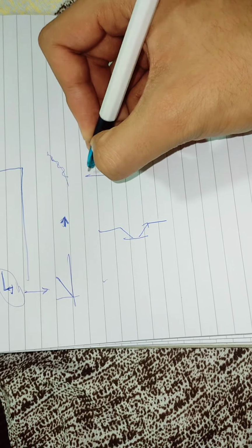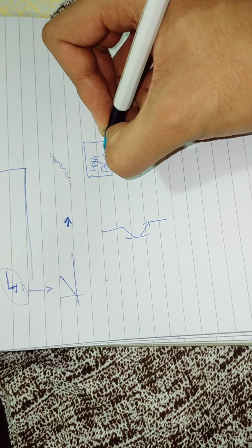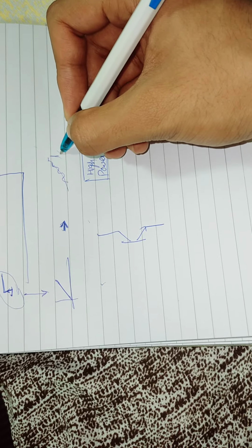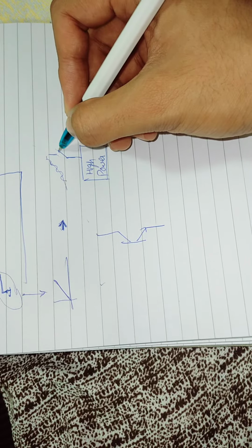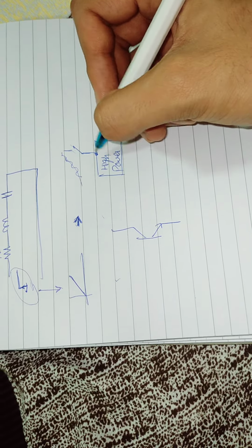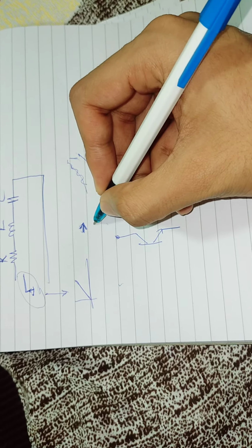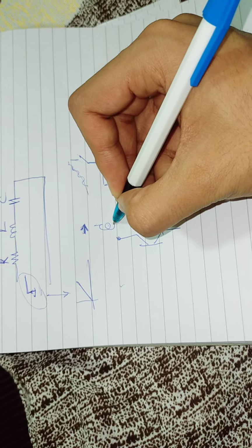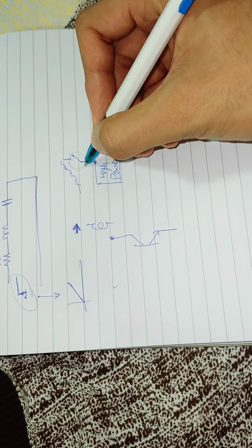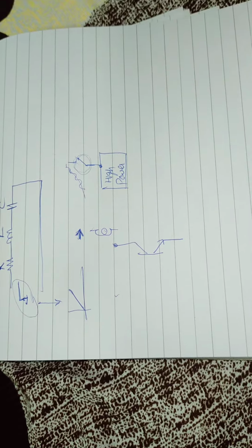They told there is a high power circuit, and there's a switch, but I can't directly turn on this switch as this high power circuit will show spark. So I have to use this BJT, and they provided a relay also. I have to use this BJT and relay as a switch to energize this high power circuit.